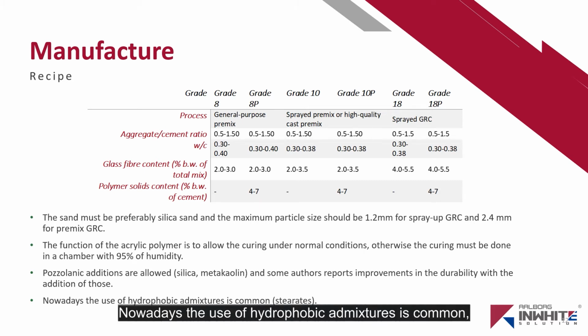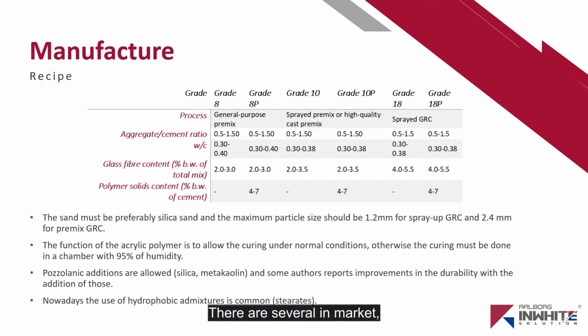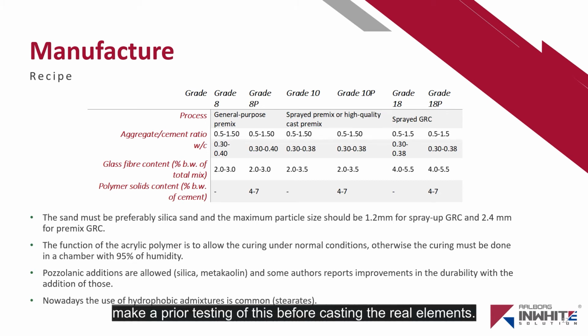Nowadays, the use of hydrophobic mixtures is common, especially for highly aesthetic applications like GRC. There are several brands in the market, and as I said before, make a prior test of this before casting the real elements.